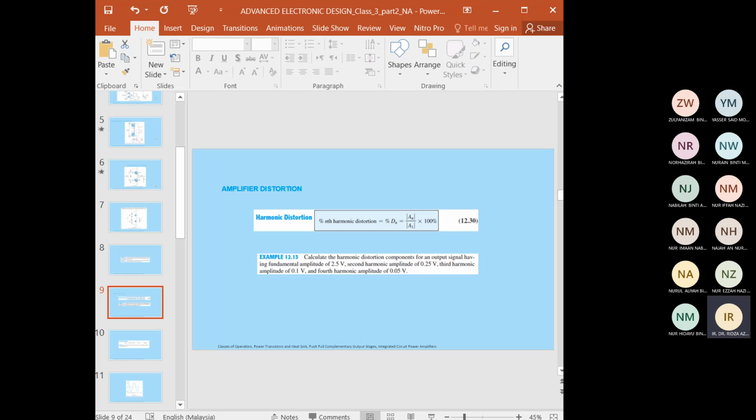For example, a signal that is originally 1 kilohertz could result after distortion in the frequency component at 1 kilohertz, and harmonic components at 2 kilohertz, 3 kilohertz, 4 kilohertz, and so on. So the original frequency of 1 kilohertz is called the fundamental frequency. Those at integer multiples are the harmonics. So the 2 kilohertz component is called the second harmonic, the 3 kilohertz is the third harmonic, and so on. Okay? The fundamental frequency is not considered a harmonic. The fundamental is the first 1 kilohertz. So that is the fundamental, then the harmonics.